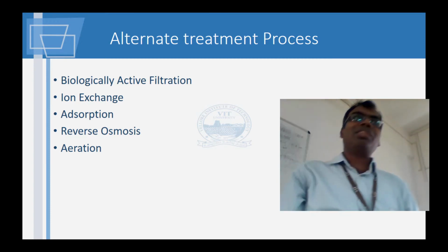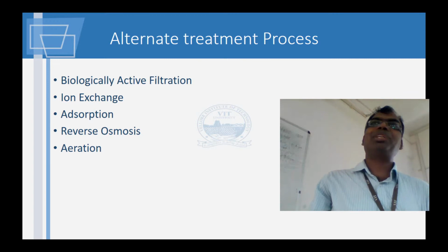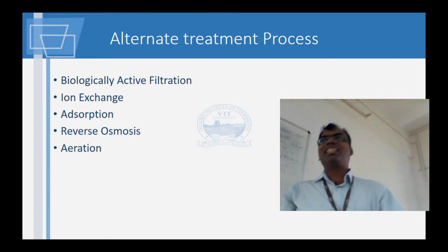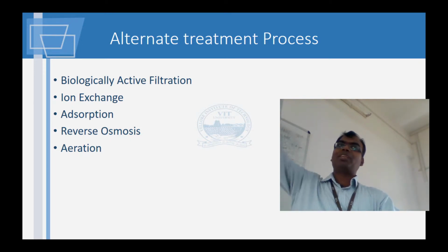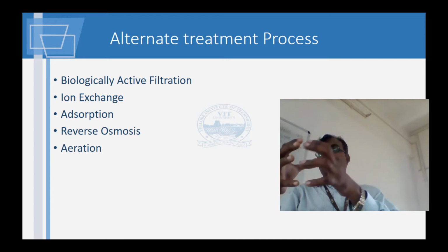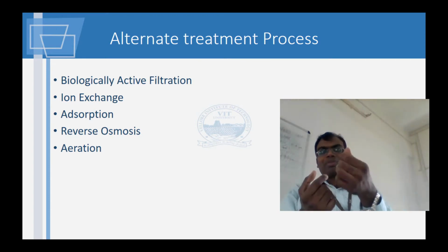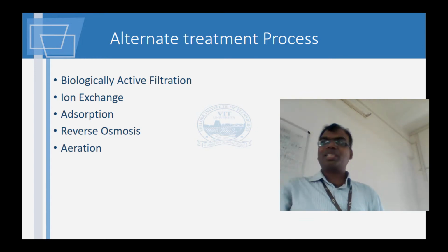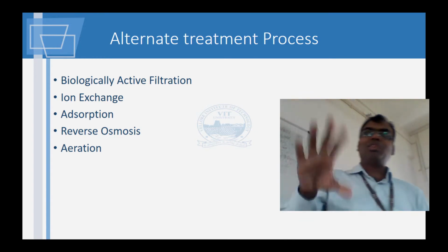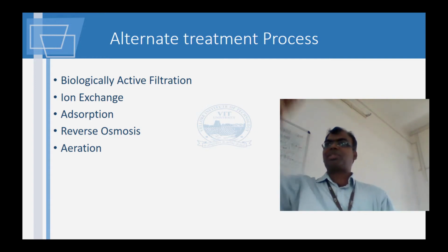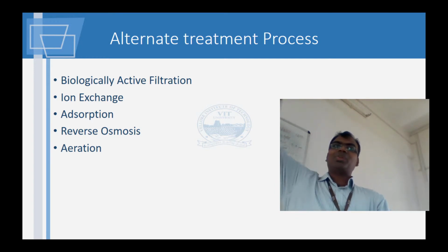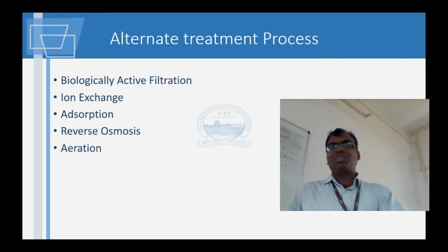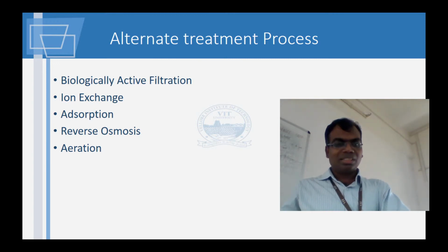Here again, the length of the pipe of the chamber is going to determine your contact period. What is contact period? Yes, the time it is exposed. So when the flow rate is very slow, the diameter is very large, and the outlet pipe is very narrow. If the diameter is very large, then automatically the flow rate inside that tube is very slow. So by the time the bacteria and virus travel from the top to the bottom, through the activated carbon, then up and overflow out into your cup, that time will be sufficient to kill all the germs.